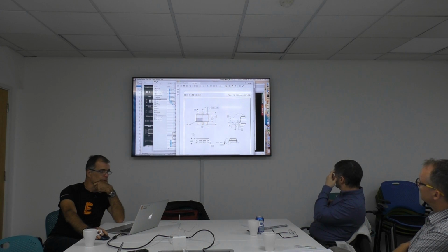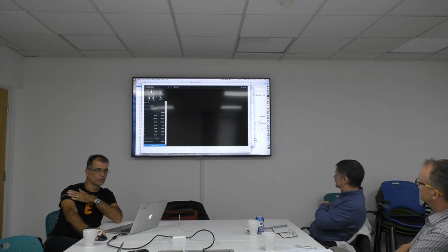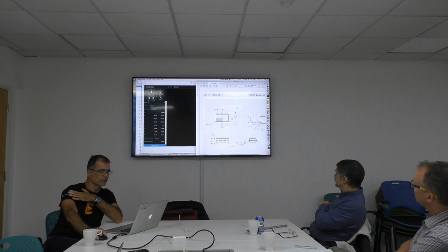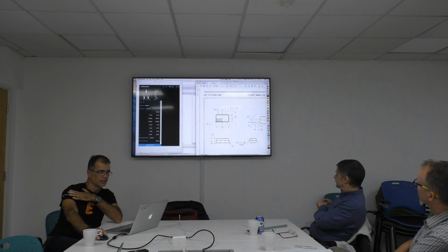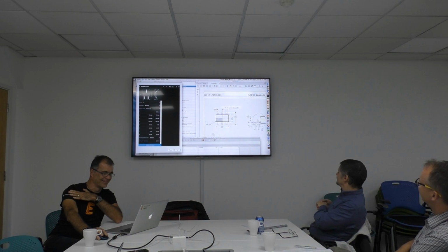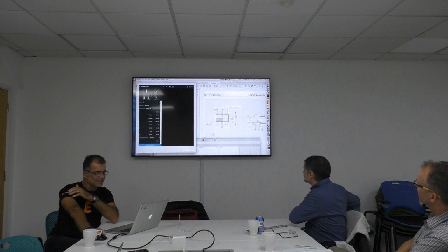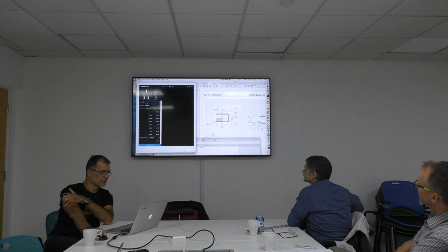Now I have to go into the package editor. Now I have to search for a fitting component. I think it's a kind of SOT, something like this. And then I have to fill in all the stuff here. Let me make this one smaller. Okay, so what we can see is how many pins do we have? 1, 2, 3, 4, 5, 6 pins. So I say 6 pins.